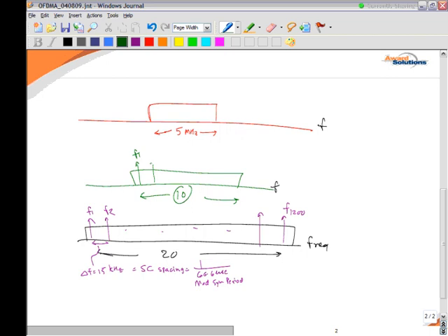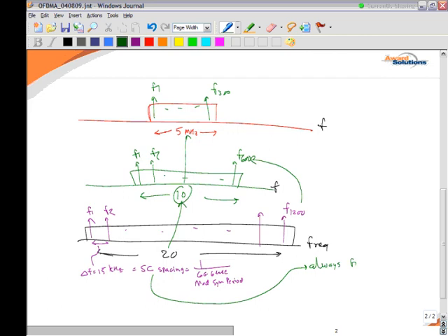So now you will have only 600 subcarriers, instead of 1200, because the spectrum is half. Then if you go even further, of course you will have 300 subcarriers. That is the basic idea. So the subcarrier spacing is always fixed in LTE to be 15 kilohertz.